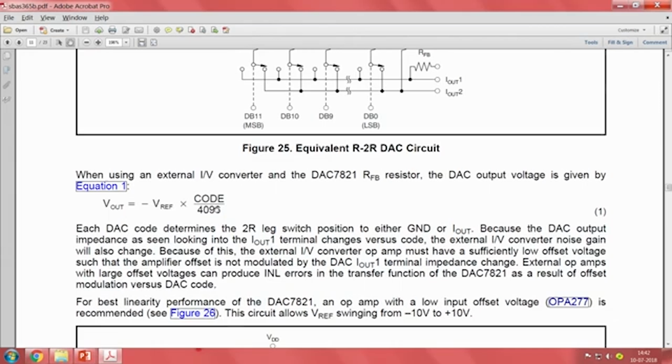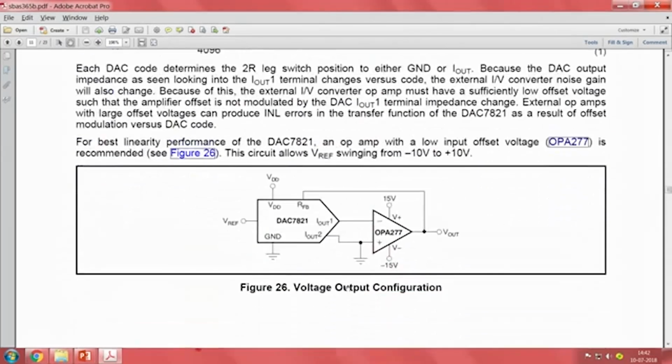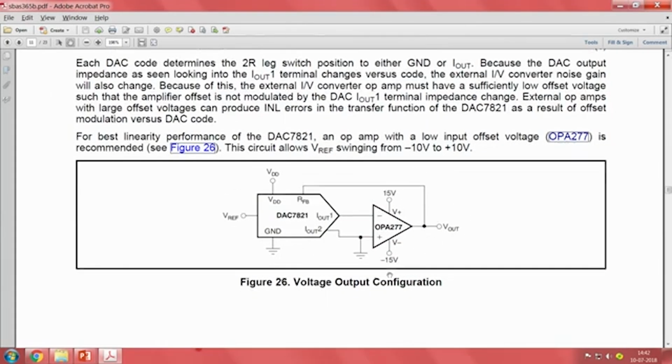Since it is a 12-bit DAC, the code can go from 0 to 4095. As we saw initially with the 3-bit binary value, we multiply it with the reference step, so that voltage is there and you get the output voltage. Then you can always amplify your output voltage to get the output signal with the necessary ranges.